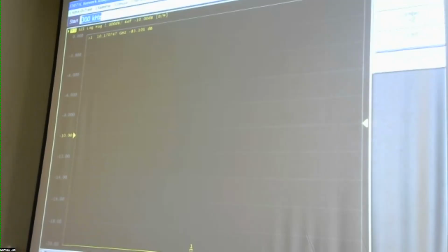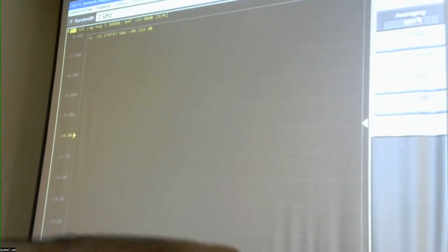So coming back to the standard settings: the frequency sweep, then you set the sweep setup, the number of points, you set your IF bandwidth, and any averaging you would like. Right now, let me turn this averaging off and keep the IF bandwidth at 2 kilohertz. So then finally, you have to choose what it is you're measuring.